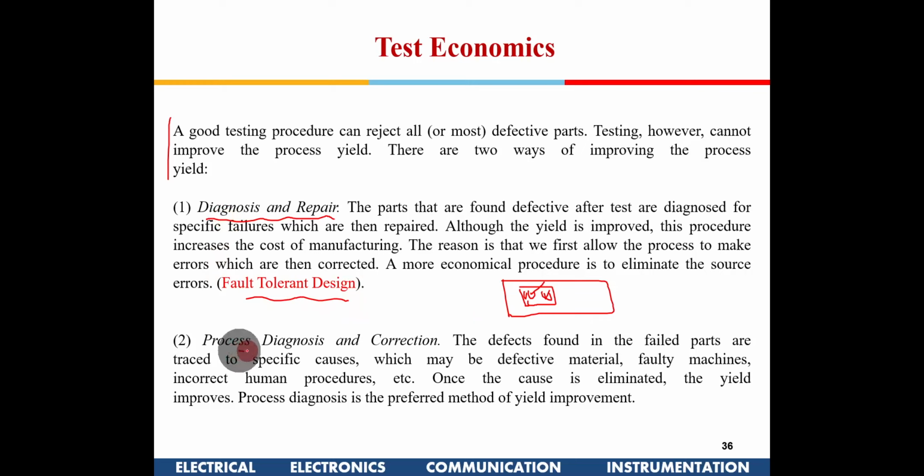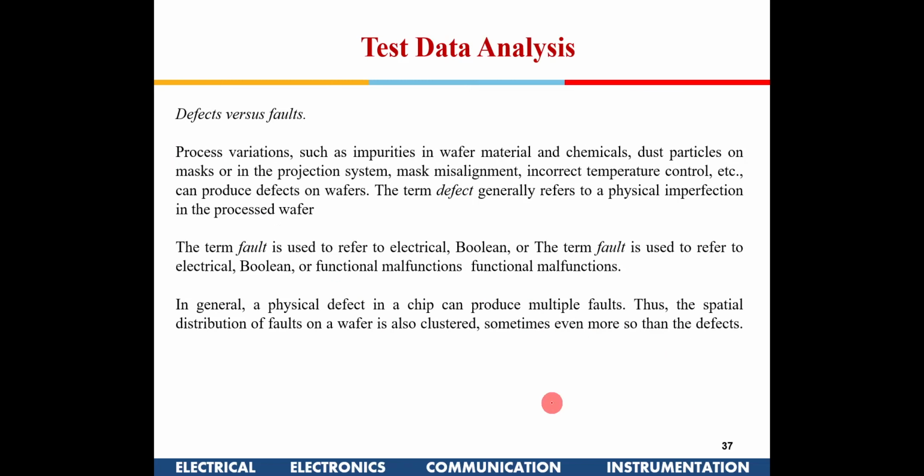And from the diagnosis, you go back to your design table and try to minimize the defects. You have to analyze why it has failed. Was there a problem in your layout? Why has that fault occurred during fabrication? Is it because of defective material, or layout issues where you have not catered enough space between the wires, or you have not catered for adequate thickness of the wire, so that during test it got burnt off? All those things can be analyzed post your testing.